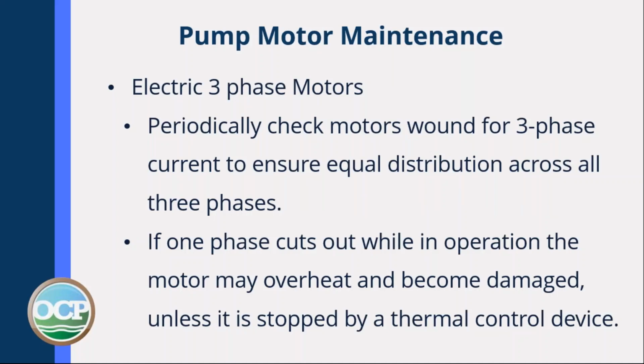On three-phase electrical motors, periodically check the motor windings for three-phase current to ensure equal distribution across all three phases. If one phase cuts out while in operation, the motor may overheat and become damaged unless it's stopped by a thermal control device.